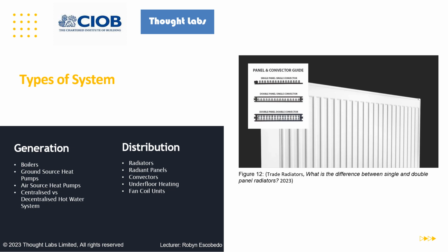Radiators also get hot, so they might not be the most suitable option in schools or hospitals, etc., where you have young or vulnerable children and adults. There are low surface temperature radiators that can overcome this, but as they are lower temperature, they will need to be a lot bigger.